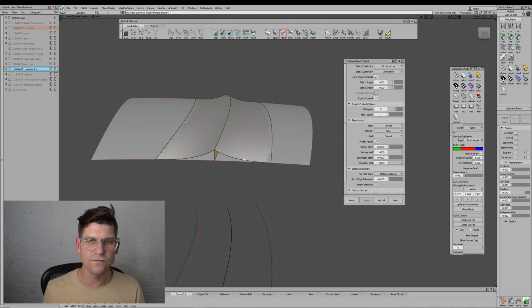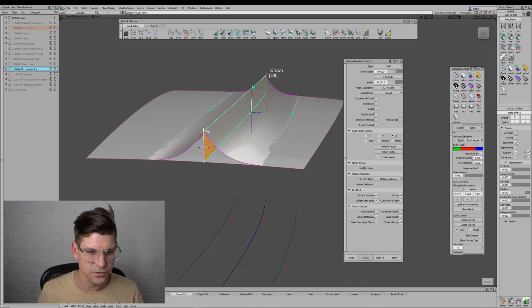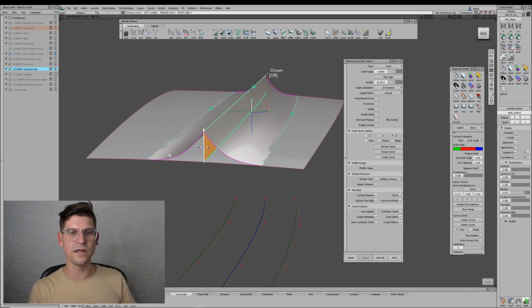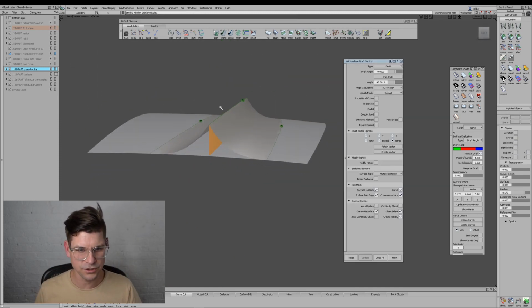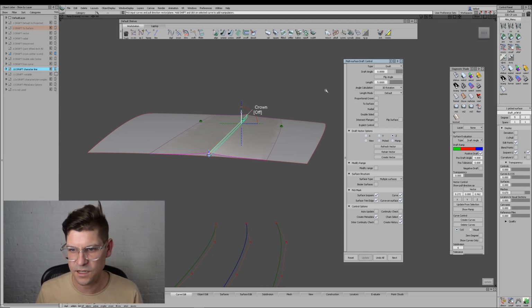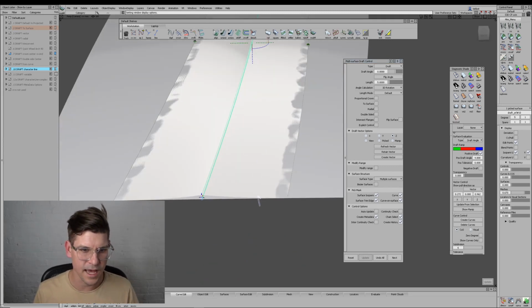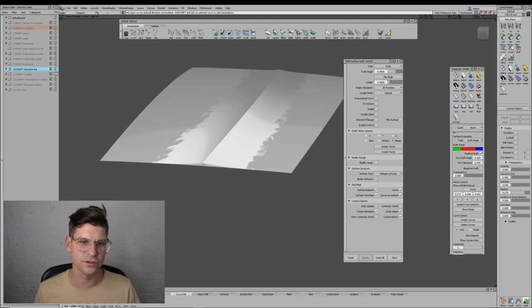So now I have the surfaces flowing to the draft, and now I can use the draft tool and use a numeric number to address how much crown or how big this shape is. And so we can be very subtle. I can come in here and just add say 5, and it's basically a normal offset from the original surface that everything's going to blend to.